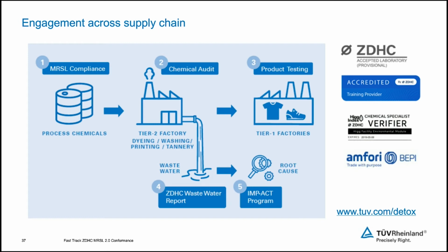Finally, as with any other process, the quality of inputs also decides the impact on the output, that is the finished garment, but also the NPO, or non-product output, such as wastewater and air emissions. Should MRSL parameters be detected in the wastewater, a well-maintained chemical inventory with MRSL conformance information via, let's say, the ChemCheck and the InCheck report could be a useful resource for root cause analysis then.